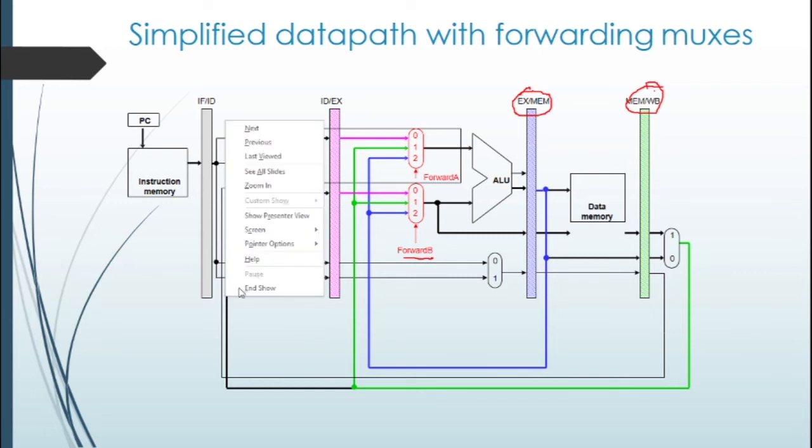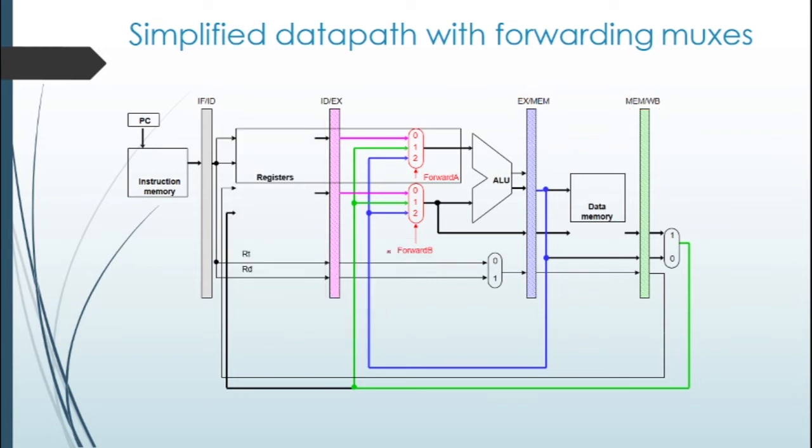So this is how a typical multiplexer will decide the inputs of the ALU. It's just taking that value from the outputs of the EX/MEM and MEM/WB, which means the previous instruction will have the data ready by the same time.